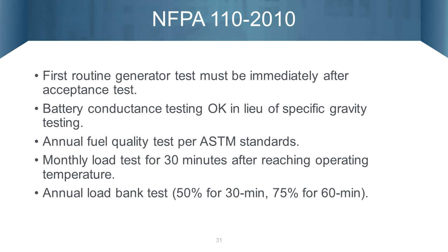It does require an annual fuel quality test per ASTM standards, and that's something that I've seen priced anywhere from $200 up to close to $2,000. Make sure that when you're working with your folks that are doing that test, they're not getting you for something over about $200-300 per tank. Monthly load test, you can't start your 30 minutes until after reaching operating temperature. And then, of course, with a load bank test, instead of being a 2-hour test, it's now a 90-minute test.